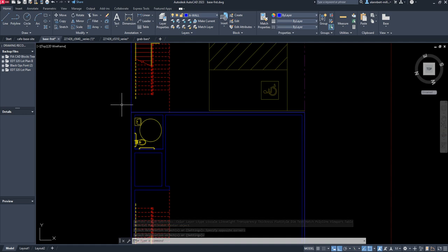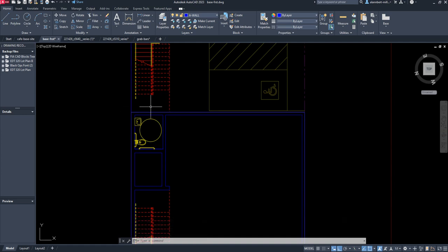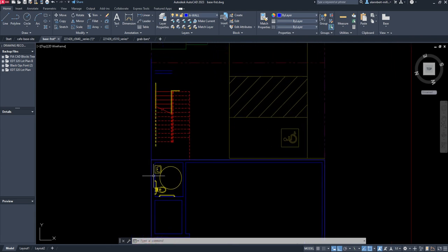and then I wanted to continue this wall. Remember, this is a lot line, so this wall is CMU. These ones are not. We're gonna differentiate that one when we get to construction drawings. So I'm gonna just select this back wall over here, and then go straight up to that one, and then I want to clear this up.